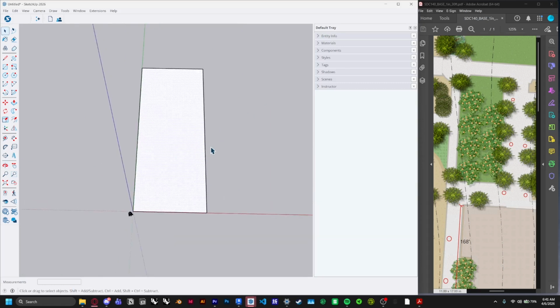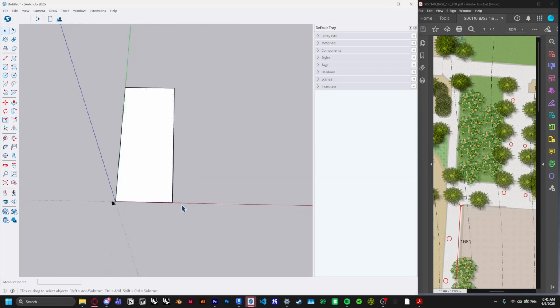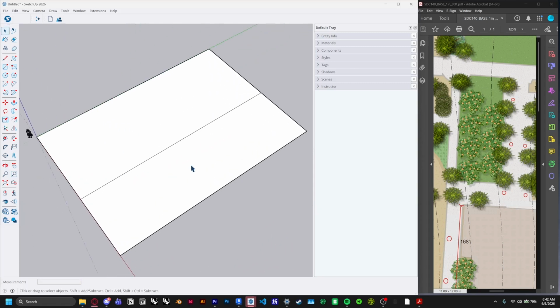So to start with the rest of the pathways around the site, let's say you're leaving Carpenter from the southeast corner. This path is 24 feet wide. So I'm going to go ahead and use the rectangle tool again, and then draw 24 feet by, so 24 apostrophe, comma, and then that distance was 81 apostrophe. And then there's that pathway right out of Carpenter.